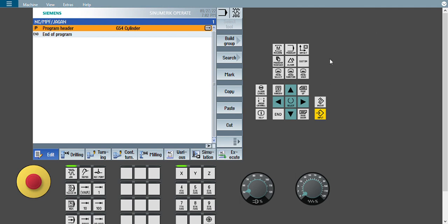In this diagram, our grooving width is 10 mm. So for making a 10 mm groove, at least we should use an 8 to 9 mm thickness of the groove tool, or thickness of the groove insert. So this is my groove insert. How a groove insert looks, I already showed in the diagram. So this is a grooving insert and this is a grooving diagram.